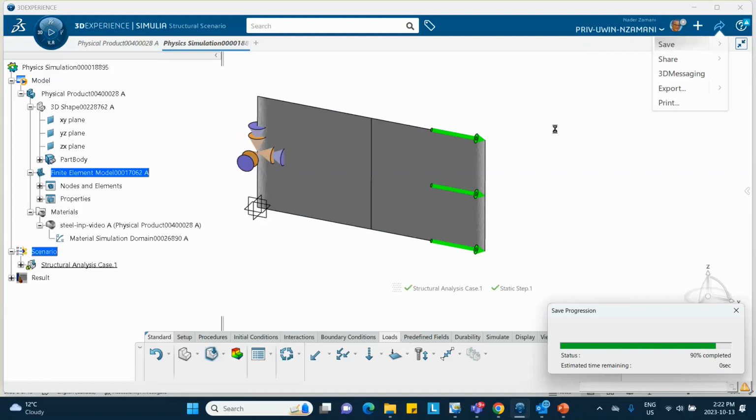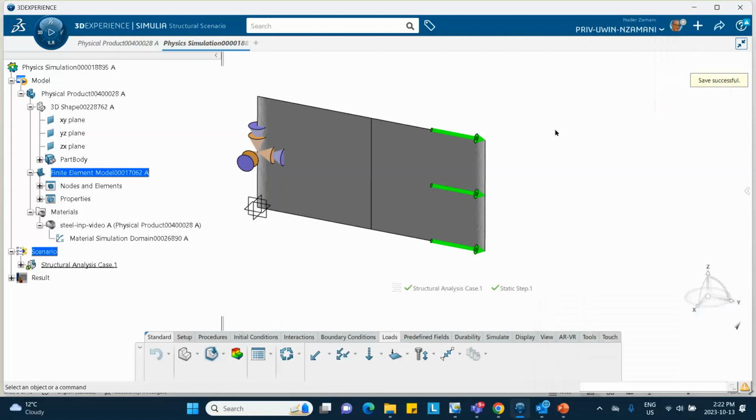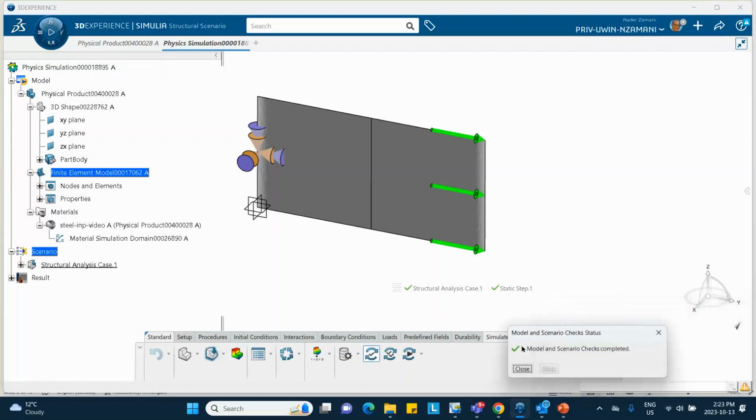Right. So let's see now. We have created it and then we're going to run it. So let me go ahead and run it. So let's do a model check. That's very quick. A simulation check to pick up any possible obvious errors. Incidentally, there may be other ways of getting the INP file, but this is my strategy of doing it.